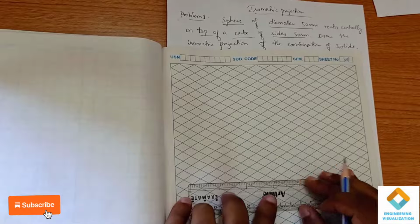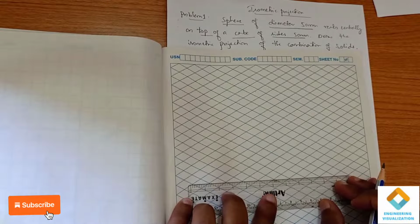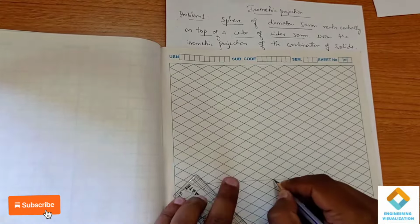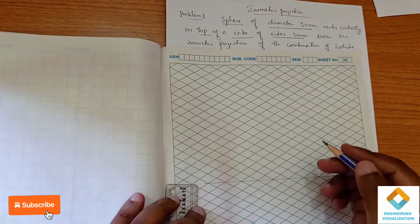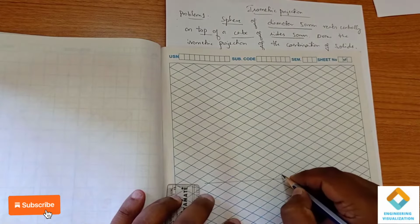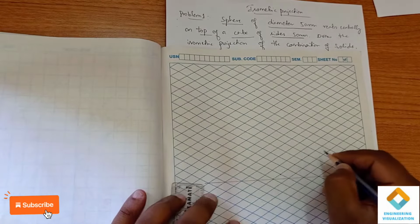Okay, first I'm going to draw a reference line here. I'll take a reference point here. Now we are using the box method to construct the cube, a cube of sides 50 mm. So I'm drawing a box of 50 here, which is 5 boxes. 1, 2, 3, 4, 5.